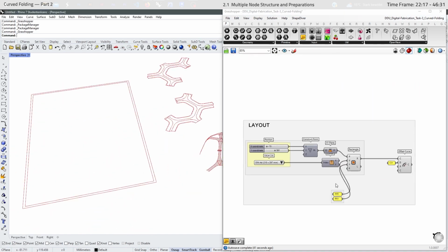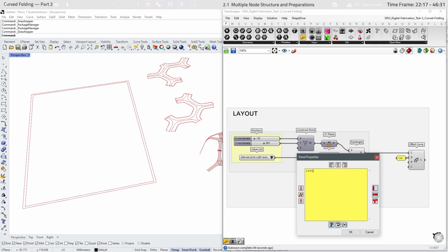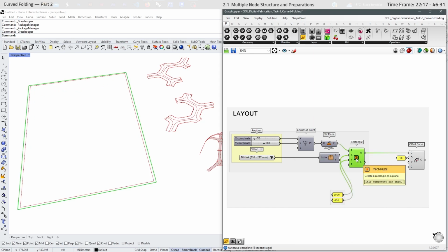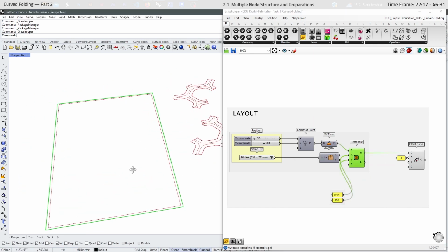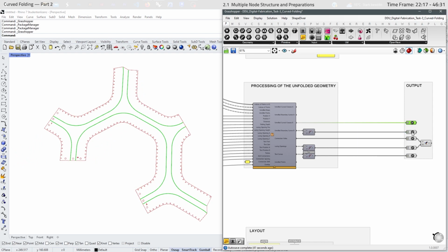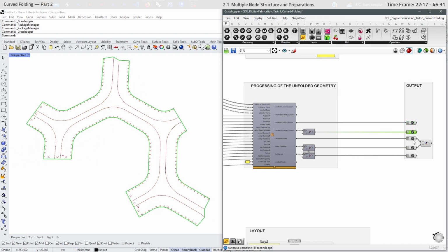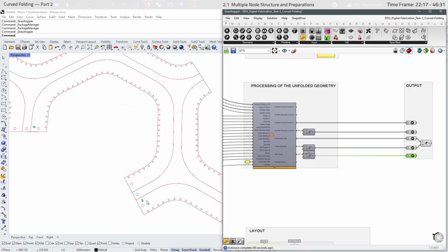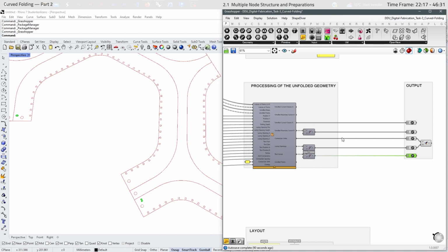And for the laser cutter, we have to change this here to 1000 by 600 millimeters. This is the size of the laser cutter at TU Darmstadt. And here we have our folding edges, our boundaries, our outer edges, and here are our openings with 3 millimeter diameter, so 1.5 millimeter radius, and also our lacing openings and our texts as curves.